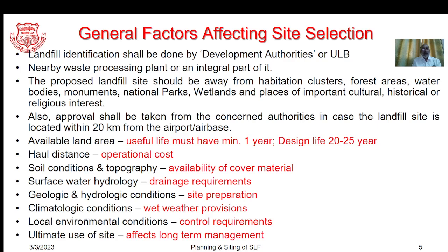Soil conditions and topography are more related to the seepage as well as the contamination of underground water sources, as well as we discussed the intermediate layers between the cells, top cover, bottom stabilization layer. So we need cover material for various aspects. Accordingly, the soil condition and topography should be favorable in order to make that cover material available.